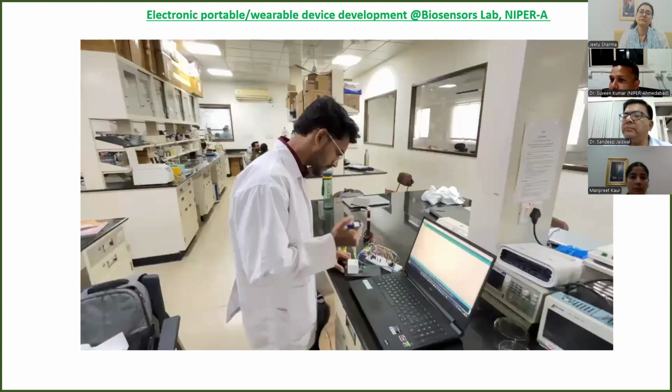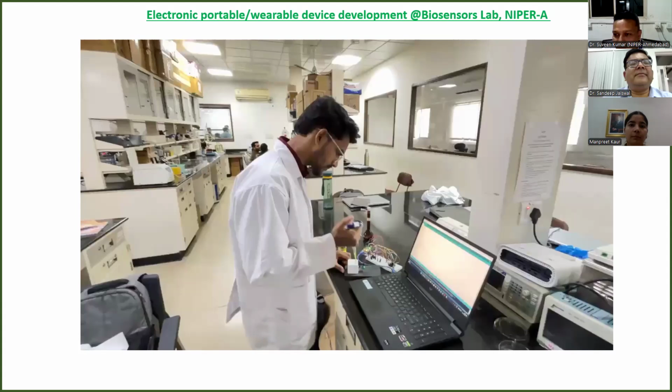Second, it should show good sensitivity, having the ability to differentiate 120 milligram per deciliter from 121 milligram per deciliter, and also 190 milligram per deciliter. If a subject is suffering from diabetes and has 190 milligram per deciliter, they do not worry, thinking, oh, I'm okay. But if the result shows 121, sometimes they will get a scare. So our proposed sensor should have the ability to differentiate these concentration values. That is only possible if your electrode is more sensitive. This is the basic parameter. If sensitivity is lower, we cannot say this is diabetes.